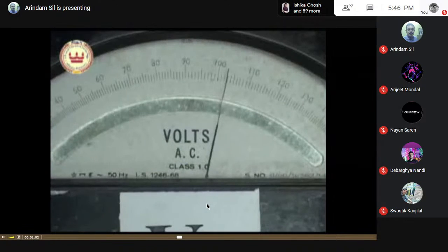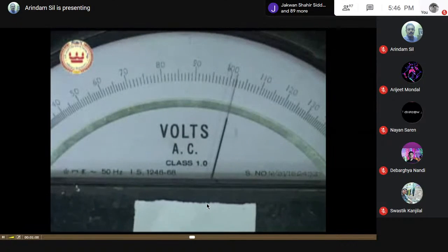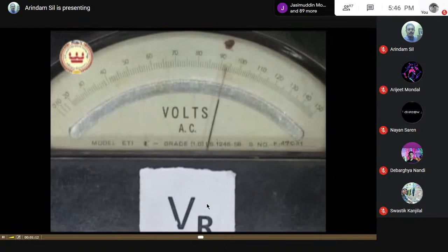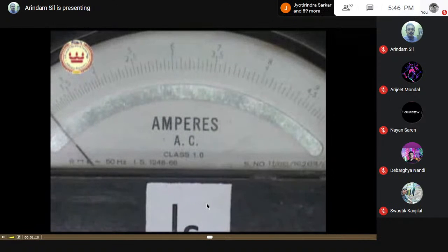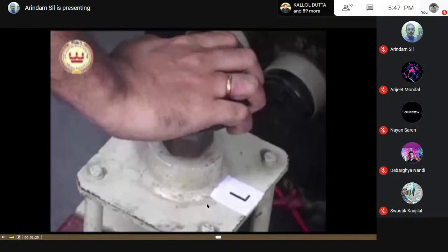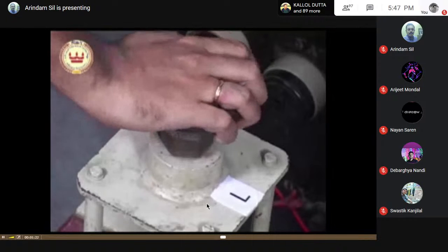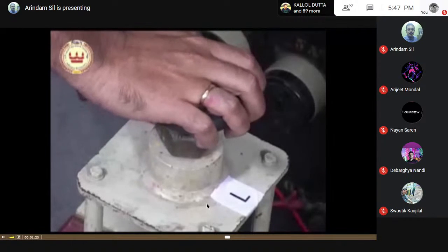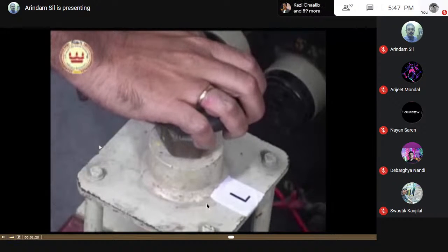Now see, both the voltmeters VL and VC indicate a reading of 108 to 109 volts. The voltmeter VR indicates a reading of 94 volts and the ammeter reading is 1.85 amperes. Now we will change the inductor once again till we achieve the desired condition of maximum line current.